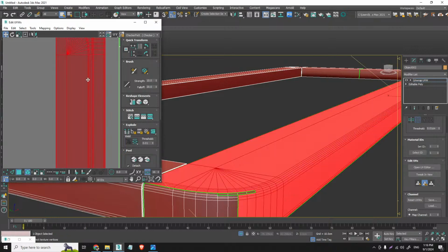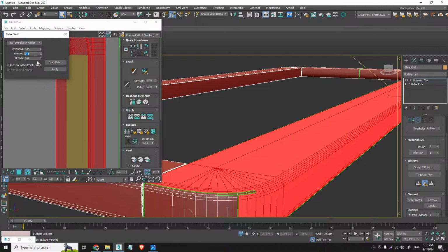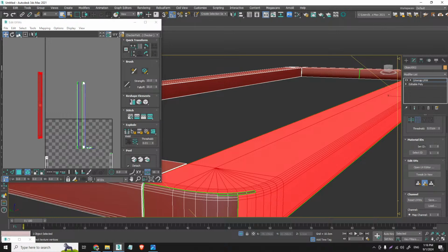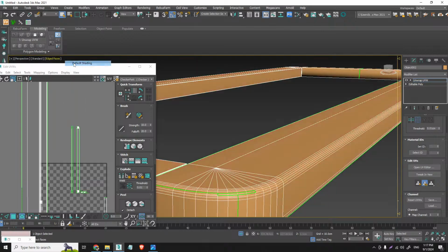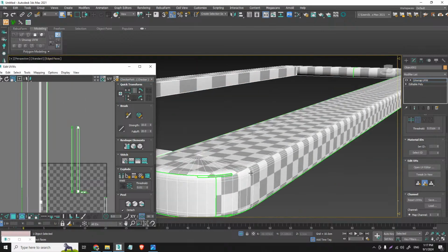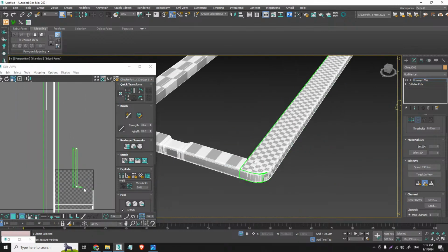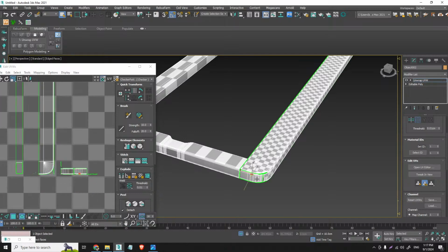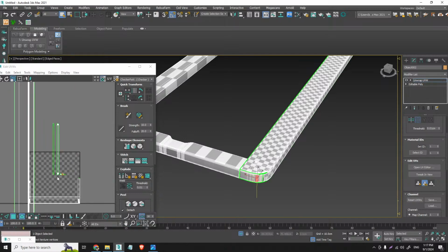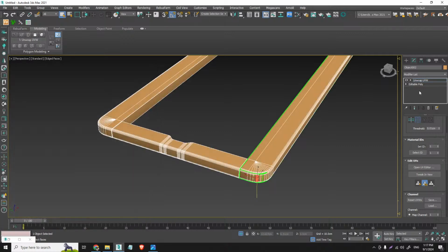And then you can just select this and go right here, hold down the left click, go to relax options and relax the bit. And as you can see right here, everything is nicely unwrapped. Everything, I mean, this part we worked on. You need to do the same thing with this one and so on. But that was the way. I hope this helped, Michael. Yeah, and that was it with the unwrapping.